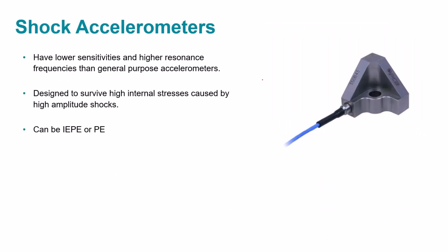Shock accelerometers, this isn't a different type. I just wanted to put this on here in case you weren't familiar with them. They make specific accelerometers for everything, but specifically there are accelerometers that are for shock. They typically have lower sensitivity, so they need a higher input, which is good because that's what you want when you're measuring a shock response.